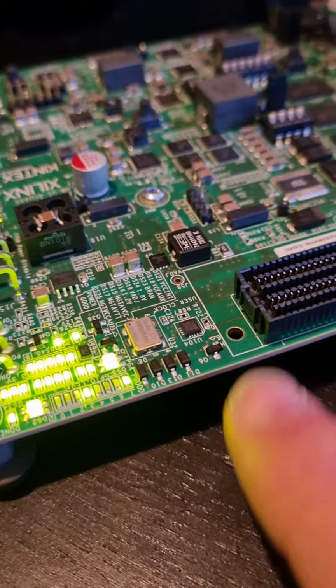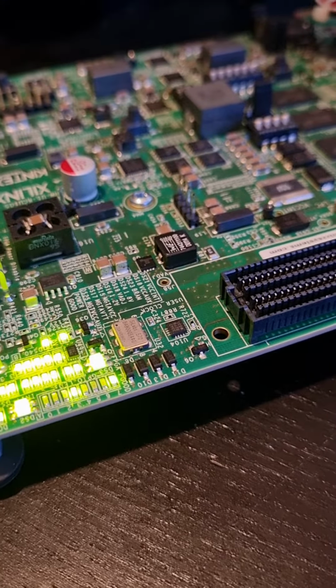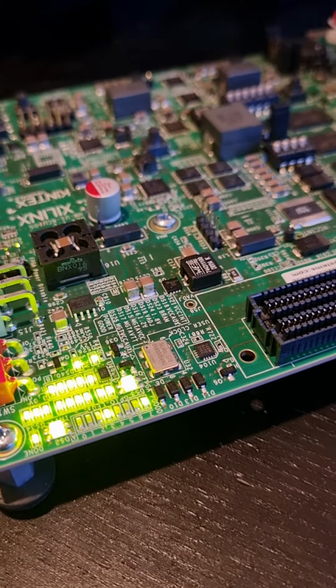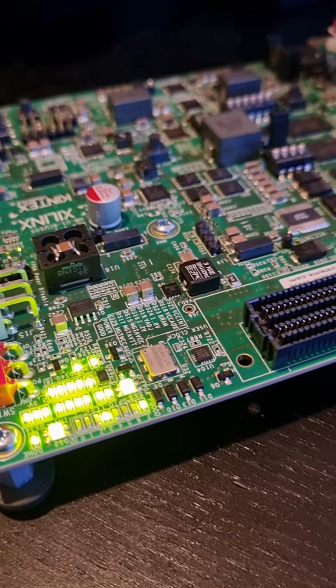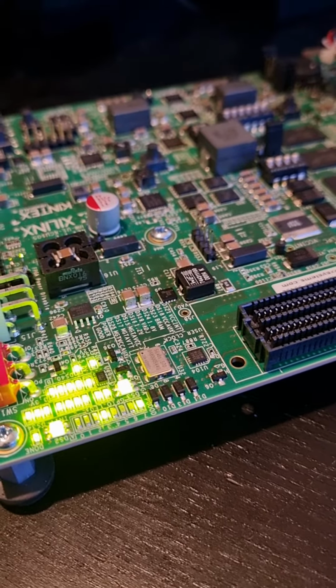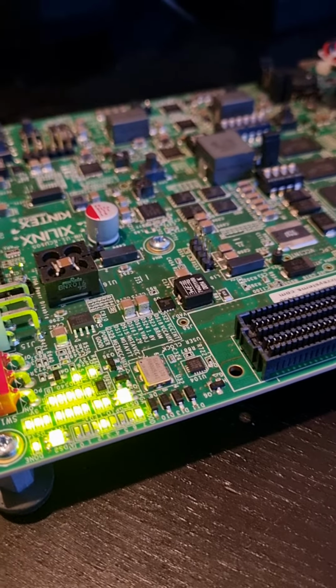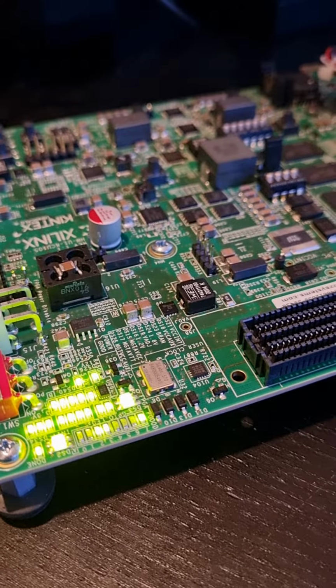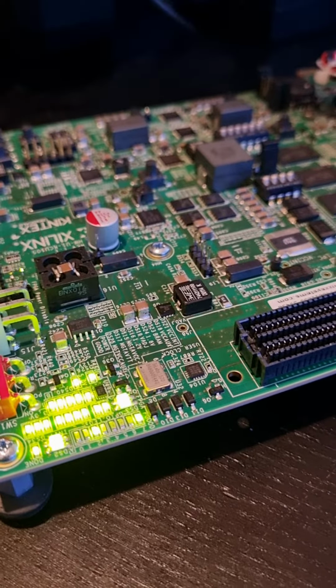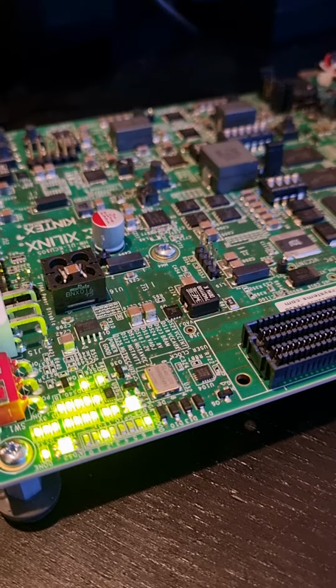and the slow pattern there. What I should say as well, you should have noticed when the partial reconfiguration stopped, the other one continued, because obviously only a small region of the FPGA was being reconfigured and had stopped working. And that's one of the beauties of doing partial reconfiguration: you can change just a small element of functionality of the FPGA design that you've got.